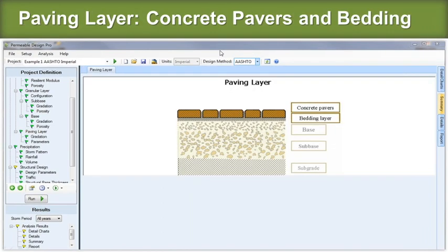As you go through this, we started at the subgrade, we went to the subbase, we went to the base. Now we're talking about the paving layer, the layer on top. So this is our permeable pavers. This is also a bedding layer, a small thickness of about 50 millimeters, 2 inches, of stone chips that we place our pavers in when we seat them into that surface.